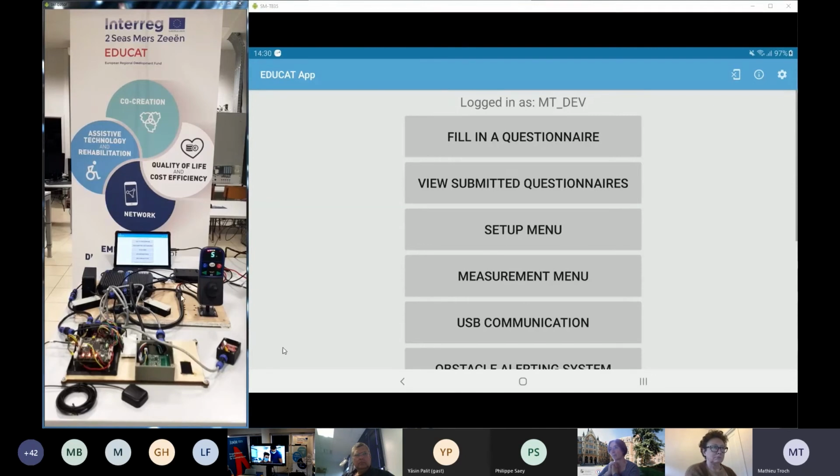So we have the joystick here, and here is the unit with the motor emulation. Here in the front we have the DMU, with next to it the TPI board. This one connects the DMU to the wheelchair. The little box on the right here is the IMU, and here is the GPS antenna. If you look closely, you can see 1, 2, 3 distance sensors, and the tablet is here, and the image of the tablet is streamed on the right side.